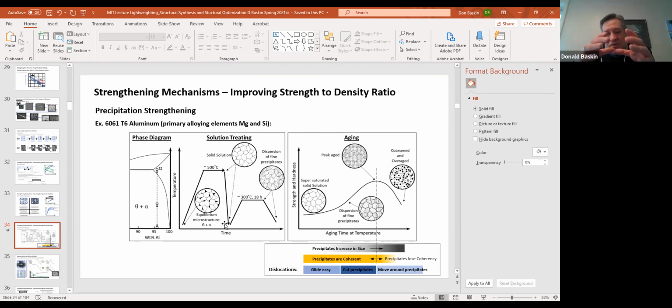What they did is they had this stack of steel laminates and wires, and then they put the armature down in there with a magnet in it, and that's how they formed the electric motor. But they had to make sure that this motor stator would stay fixed in the aluminum housing. So they heated up this aluminum housing, and when it was hot, they jammed in the motor stator, and then let it cool back down.